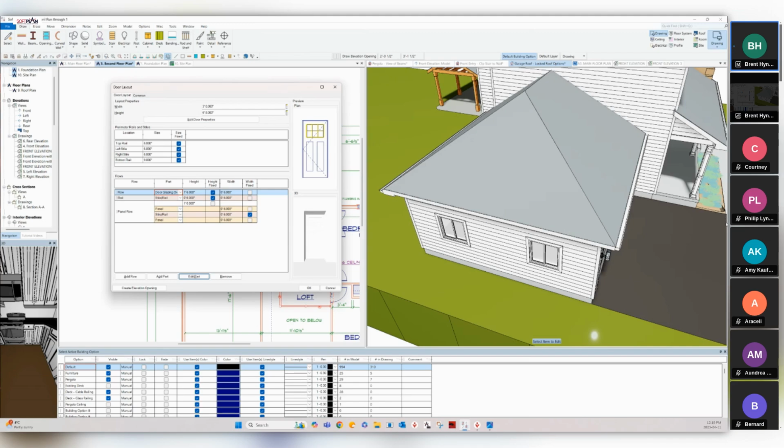Additionally, in these areas, so I'll just click where I had added a panel. This is where we could put in a sliding window, a glazed area, the door glazing, which we already had, round tops, panels and stiles and rails we've used already. We put in quarter rounds, ellipticals, and we can also add in 3D symbols. Now the 3D symbol is going to stretch within that space, but what we can do differently with this is it doesn't stretch across the entire width. So if we were to put in something that was a 3D symbol, like a raised panel, then we can actually have it stretch properly down the middle and across the sides. All right.